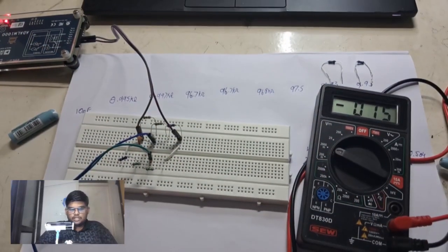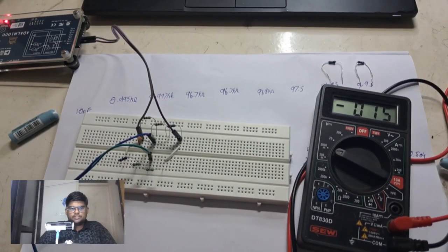You can see the output voltage in the multimeter, which is similar to the output voltage we got in part 2 because the capacitor doesn't allow any DC voltage to pass through it. The ADALM kit can't measure the voltage across A and B because it only has one ground. Traditional oscilloscopes have two separate grounds. So it can do only one thing: if it is giving the input, it can't measure the output.